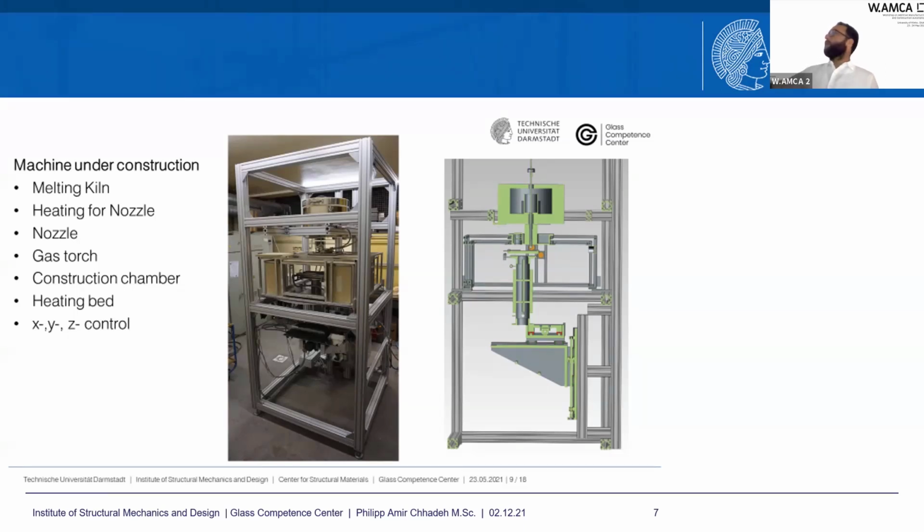Then we have to face the other issue. If you want to put a glass plate in for the next print, the heated plate needs to cool down so that we don't get a thermal shock. We can also think about having an oven on the side with a preheated glass plate in there and put it in. I think this is a bit advanced, going to mass production thoughts right now, but we also have this in mind so that we don't waste too much energy in just printing one specimen a week, just to cover this thought.